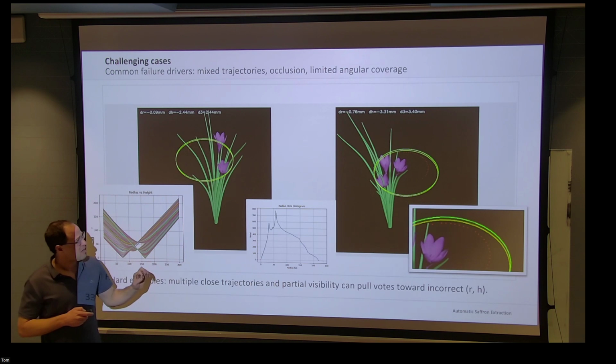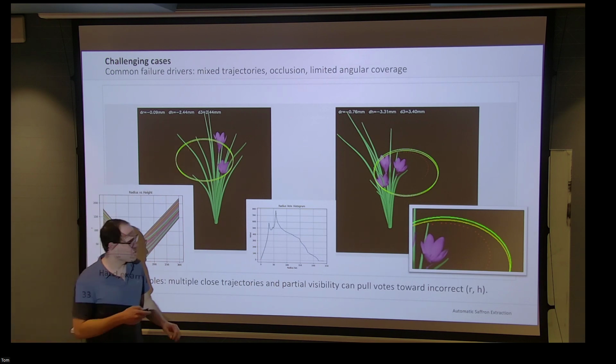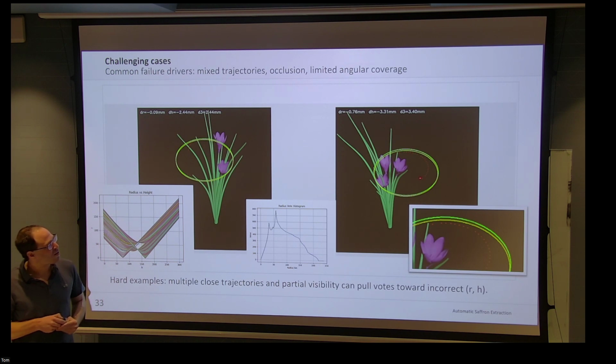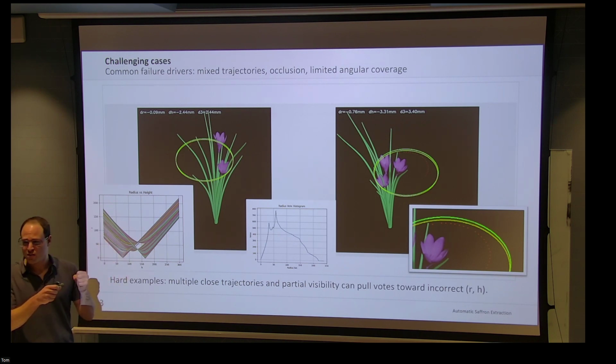What's the problem with 3 flowers? You can see here what we call stealing points. This is the problem. All those points that are not on the ellipse, the red points, belong to a different flower. While we rotate the flower, another flower gives our algorithm the idea that this is the candidate for picking, because it's the lower one, the most seen one.